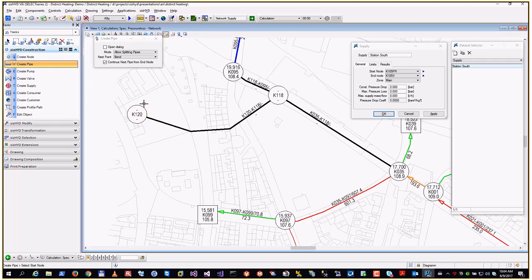So when I here move to the node, now pipe construction started. I need a first node, so an existing node is detected, it's highlighted, and click will snap to it, so it snaps and starts at the center. And when I move to a possible end node, the node is highlighted again, and clicking means I accept it as an end node.